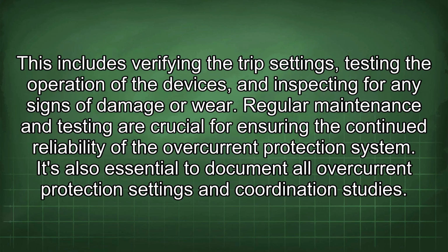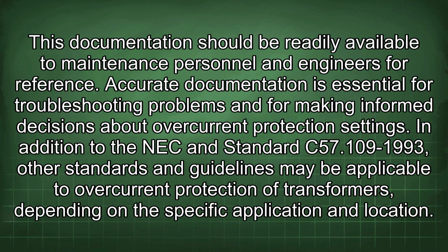It's also essential to document all overcurrent protection settings and coordination studies. This documentation should be readily available to maintenance personnel and engineers for reference. Accurate documentation is essential for troubleshooting problems and for making informed decisions about overcurrent protection settings.